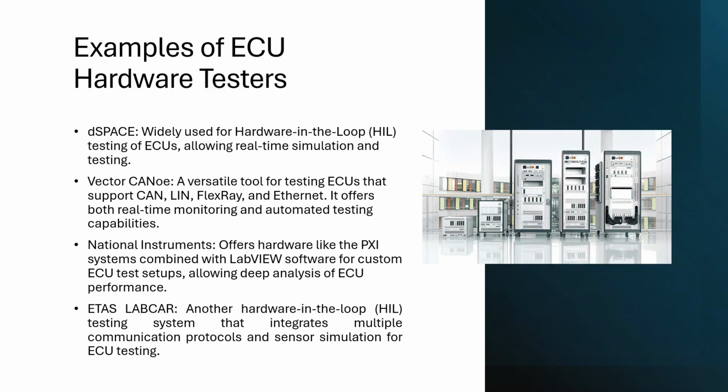National Instruments offers a wide variety of PXI platform systems combined with LabVIEW software for custom ECU testing, and allows deep analysis of ECU performance. ETAS LABCAR is another ECU hardware tester which supports hardware-in-the-loop testing that integrates multiple communication protocols and sensor simulation for ECU testing.